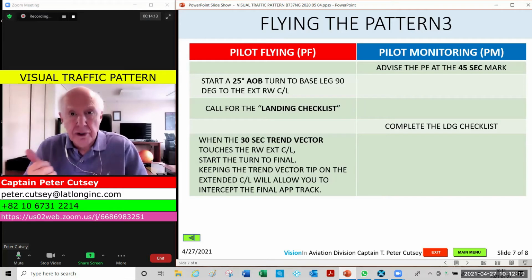And look for the PAPI. Once you see the PAPI usable, then adjust your rate of descent in accordance with the PAPI. You'll find around 850 feet a minute, but remember, this is not an IFR approach. This is a visual approach. So your eyes are outside, inside, outside, inside.